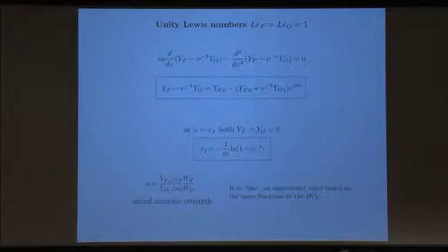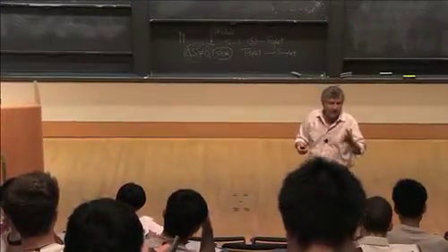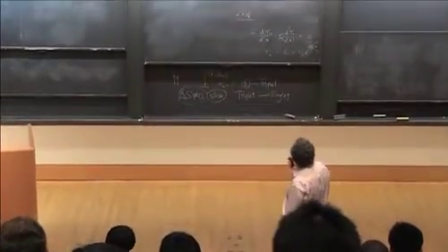I'm going to show you the solution for this simple one-dimensional problem. It's also because the equations are easily integrated in this version. That's why I chose this to start with. But I'll show you two ways of finding a solution. One, when you assume that the Lewis numbers are all unity, and then I will generalize it for non-unity Lewis number. Now, for unity Lewis number, the idea is that you can use the coupling function that we have discussed earlier. So here is one of them.